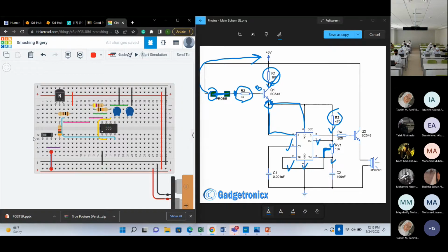Now I want to say that when the switch is on this side, don't do anything. Don't do anything means that this is empty, right? So there is no connection between the two. If there is no connection between the two, what is the voltage here? What do I need to connect this point to? Either to nothing, because there is nothing there, or I already know I want this voltage to be set to low when there's no raindrop, correct? So I'm saying that there's no raindrop here. Low is the ground, right?